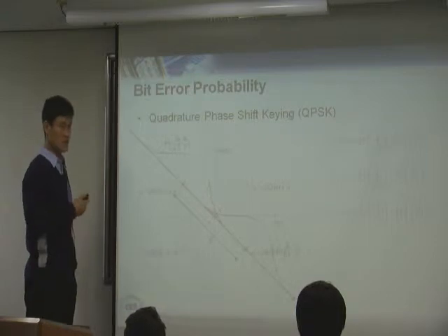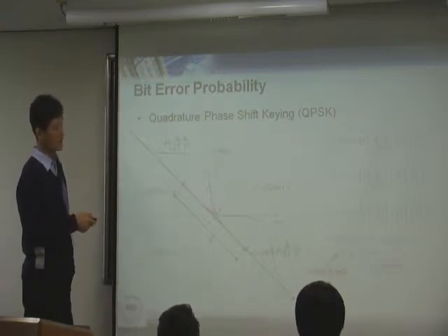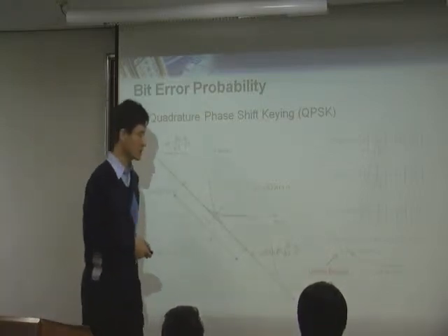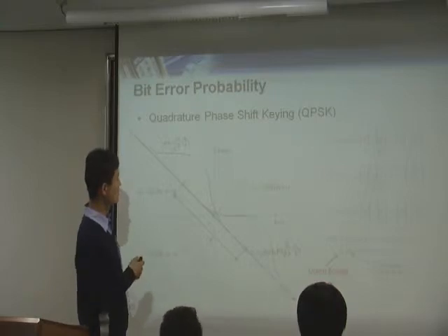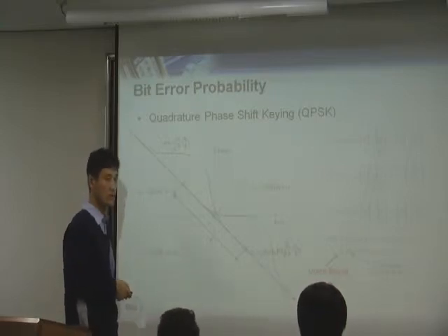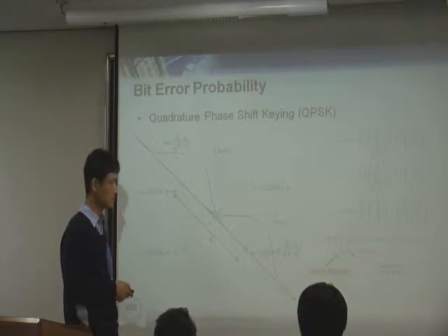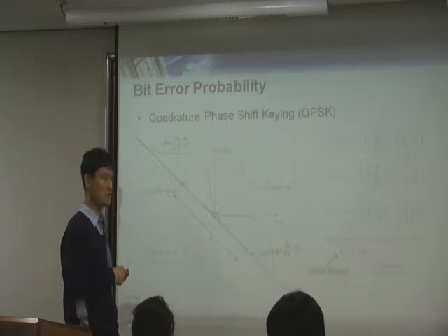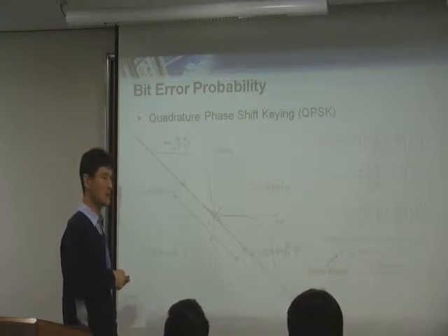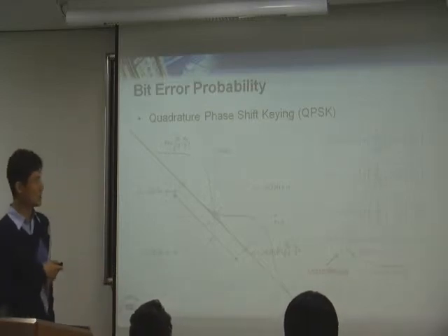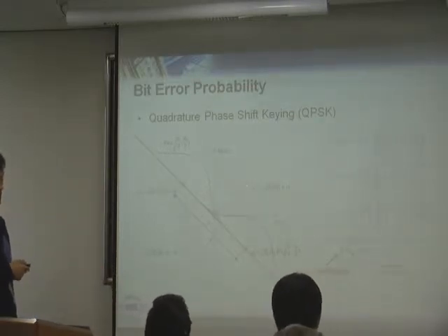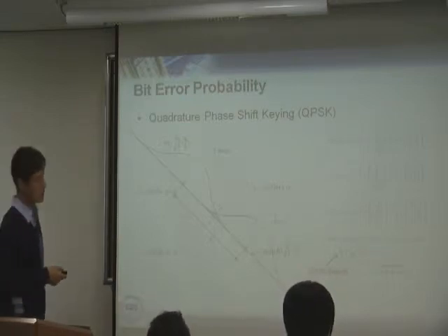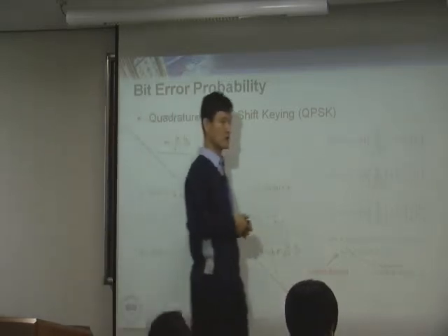Right. So what needs to happen is that we have to think about these three different cases separately, in order to make it accurate. But typically, we use a union bound to calculate the bit error rate. If you think about each of these separately, it's pretty much difficult. Sometimes it is impossible. Therefore, what you do is that you can think about one error case with a higher bit error rate. And then you just multiply the number of cases.